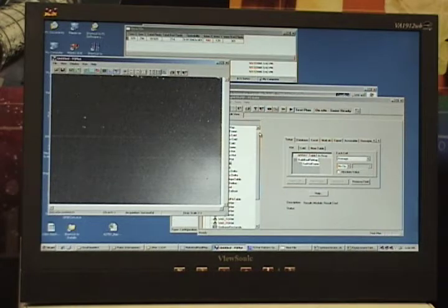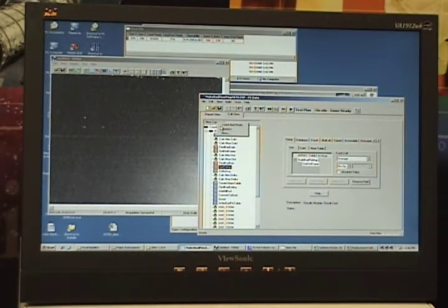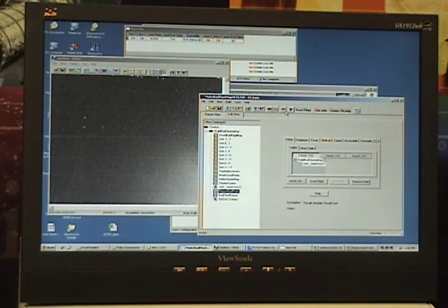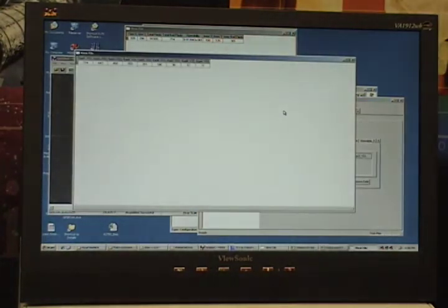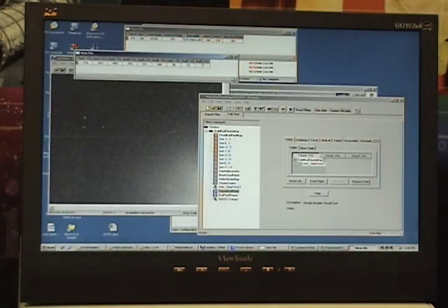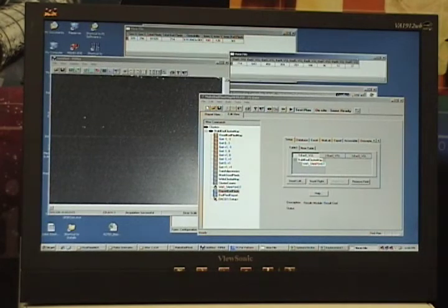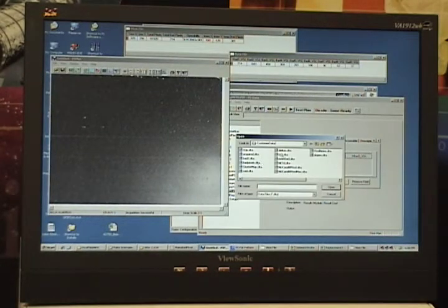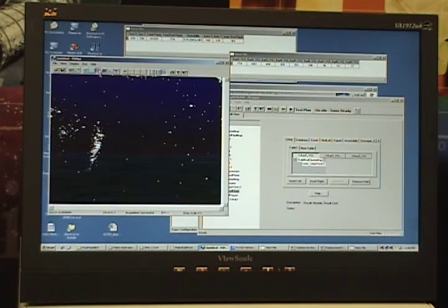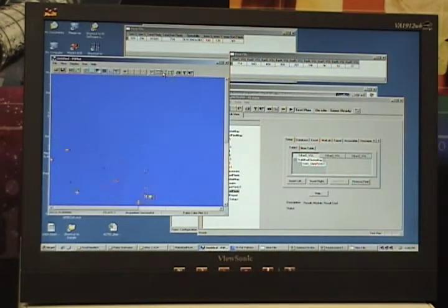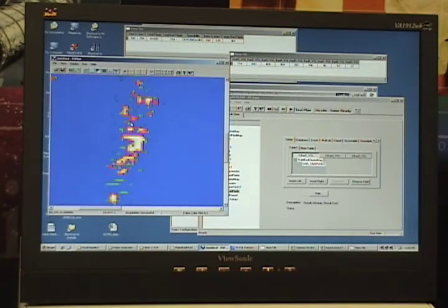Next, we can count clusters of bad pixels. If we define a pixel as having 8 neighbors, we can calculate each bad pixel's cluster count as the sum of all its neighbors. We run the test plan, and it reports clusters of size 1, 2, 3, etc., up to 9. We can display the cluster map in color, then zoom in to see the different cluster values at each location.